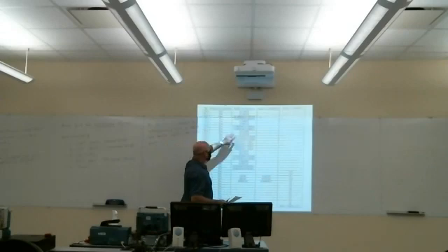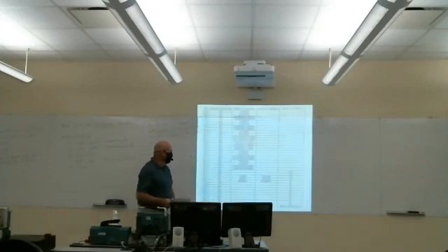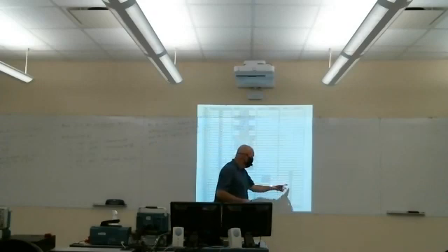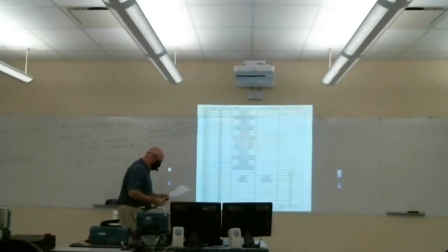So for these set of pins, the selection 1 and selection 0 bits should only be 0, 0, or 0, 1. And you shouldn't have them 1, 0 or 1, 1. But then down here for the 4 function pins, you've got all possibilities to select. These are actually the ADC, analog to digital conversion channels.